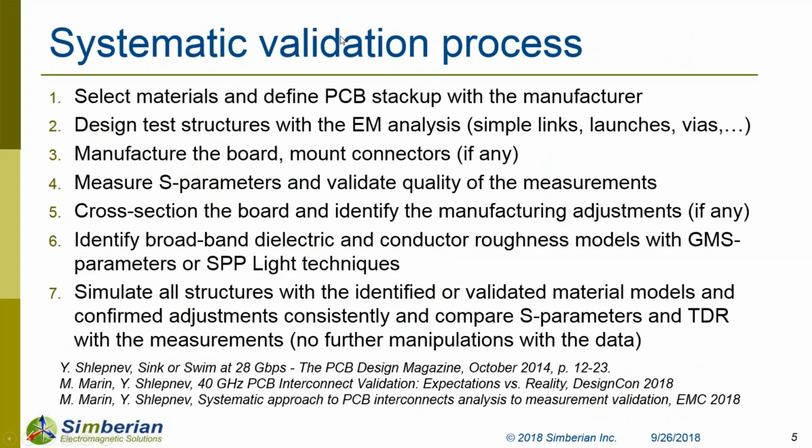So, what is the systematic validation process? Usually, the purpose of building validation boards is manifold. It can be used to pre-qualify the PCB manufacturer or the type of new laminates you're planning to use on your next production board. You can do it to benchmark your EDA tools. And you can also use it to learn more about high frequency measurement in the microwave to millimeter wave range. So how does the validation process begin?